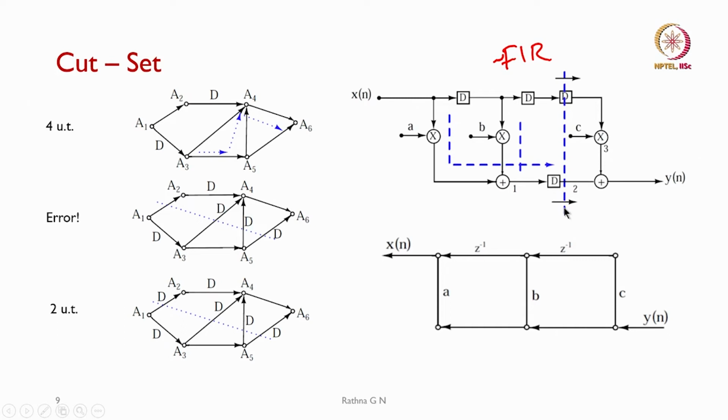The disadvantage is that we will be adding hardware to this structure, and the first output is going to be delayed by 1 clock cycle, and later on we will be getting an output every T multiply plus T add from this structure. So, we said, can we avoid this cut set by modifying our structure itself?